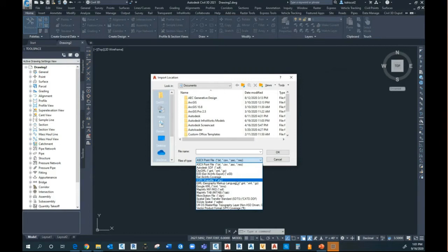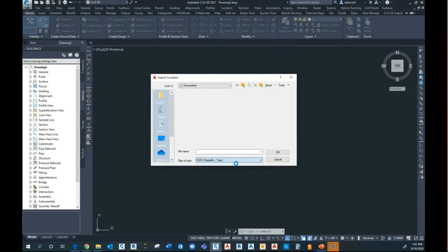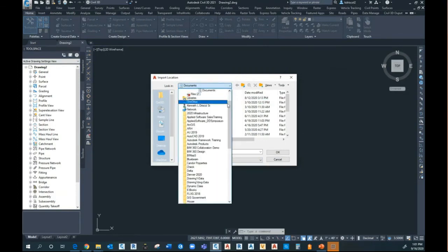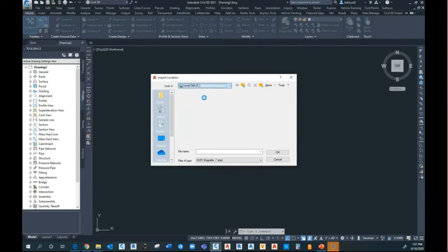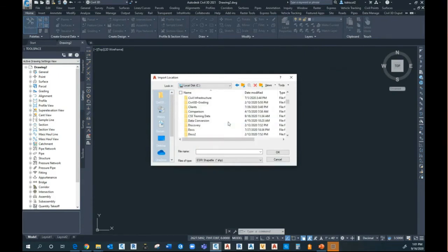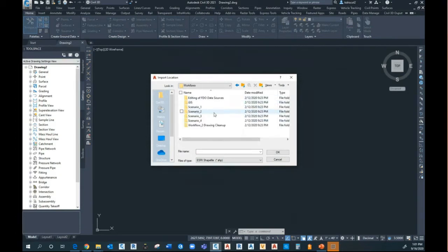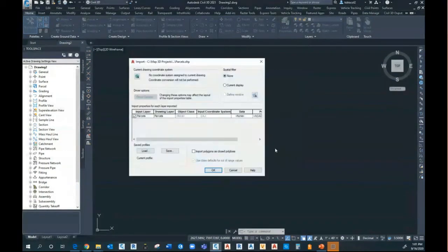If I wanted to import an Esri shapefile, I would go to the folder where the GIS specialist added that data and told me where that folder was. Then I would go to that folder under Map 3D, under Map Data, and bring in that data. From that, I could bring in my parcels. Again, this was the old way of doing things.